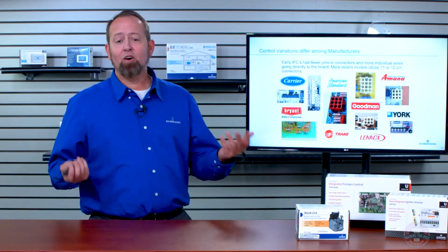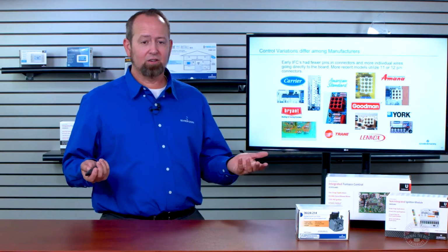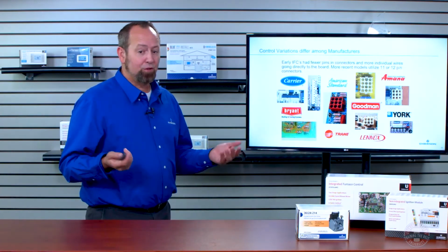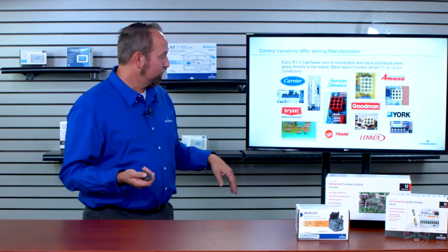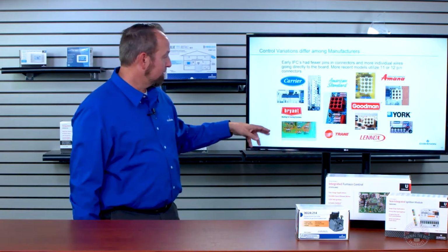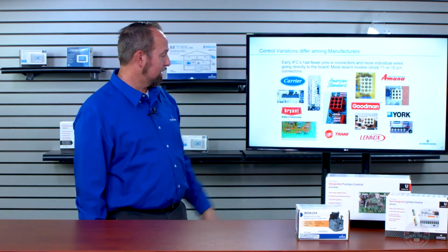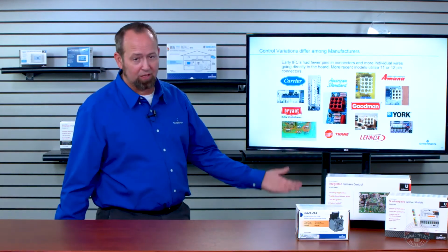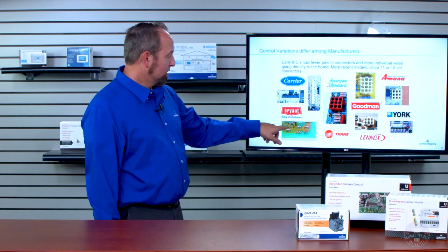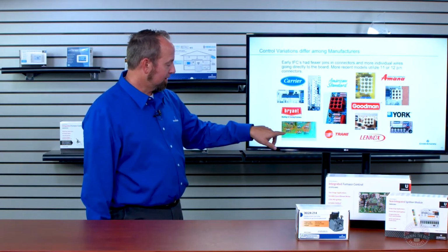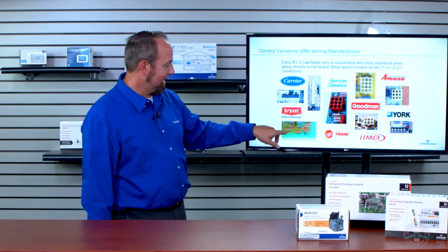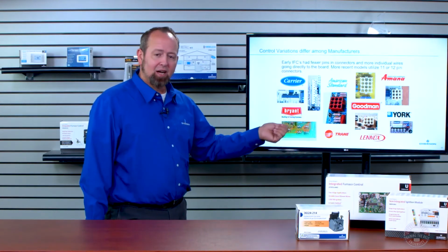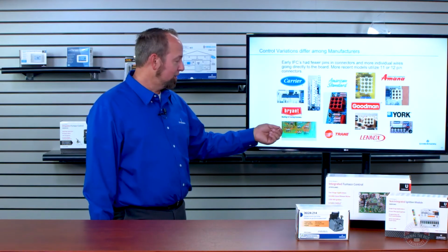So you have all kinds of variations with this. The early IFCs had fewer pins. Some of them might have had 6, 9 before they got to the 12. The Carrier ones had the 11-pin inline. Here's a York with a 7-pin. There were different styles, different pins. The early models simply show limit 1, limit 2, gas 2. They were actual pins or spades that wires would plug into individually.